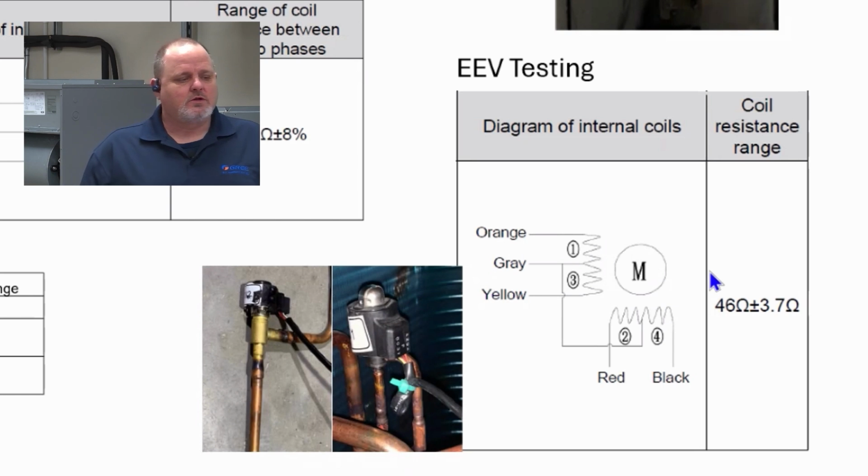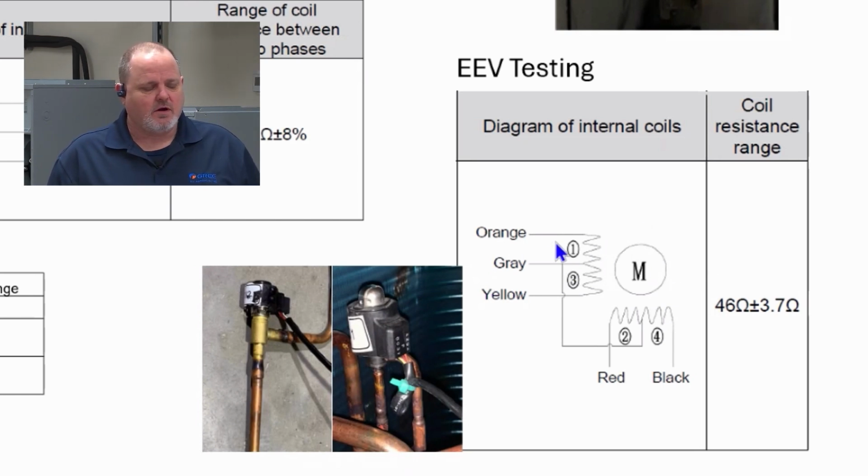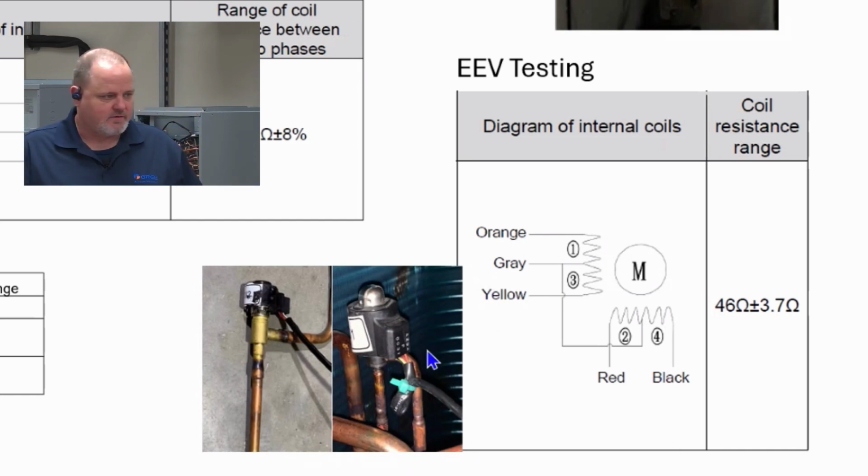The other thing you want to do is make sure, and this doesn't happen very often, but we have seen it, is each wire to ground. You should have no resistance. If you got resistance to ground, take that power head right there off of that valve body. You're probably going to find it corroded, and what's happening is you're getting resistance through the coil to the armature. If you clean that up really good and put it back on there, just using some emery cloth, steel wool, and put it back on there, your ground will probably go away. So kind of a tidbit there.